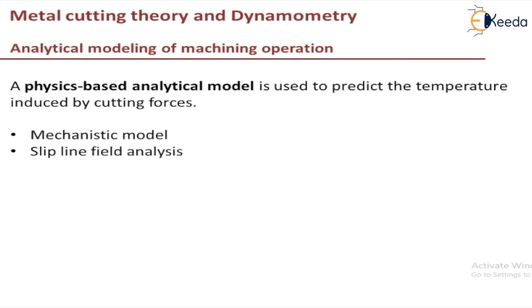Apart from this analytical model, there is also the FEM based model, that is numerical modeling. FEM based models are able to simulate the cutting process for 1 or 2 revolutions and predict any kind of physical phenomena describable by finite elements. That is, if you can do the pre-processing in FEM, then you can simulate the cutting process for 1 or 2 revolutions. You can give the boundary conditions and other things in the pre-processing, then you can simulate 1 or 2 cutting operations. This is quite an accurate method, but the computation cost is expensive compared to analytical modeling.